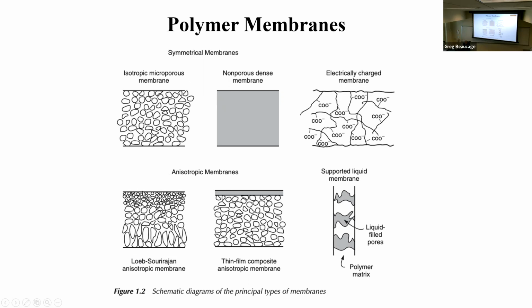Solvent, non-solvent phase separation membrane, where you have your polymer in a complex mixture of solvents and some non-solvent sometimes, and then you drop it into water. It's always water as a non-solvent. And then it'll precipitate out, and there's a gradient in the process. And at the surface, you get a thin separation layer. You can make the whole thing in one pop, right?